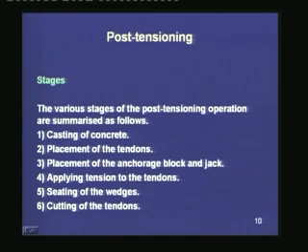Next, tension is applied to the tendons, and the wedges in the anchorage blocks are allowed to sit so that the tendons do not slip from the anchorage blocks, and finally the excess amount of the tendons are cut off from the ends.